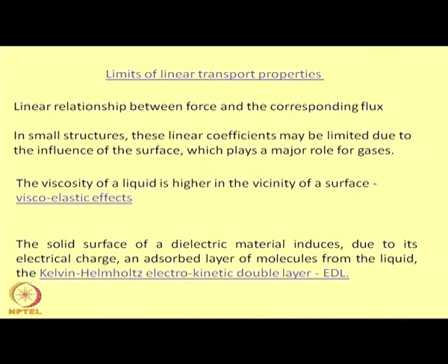or EDL in short. So, the presence of EDL, the presence of an immobile layer of liquid very close to a dielectric material, creates a situation which is different from the bulk flow that we have discussed so far.